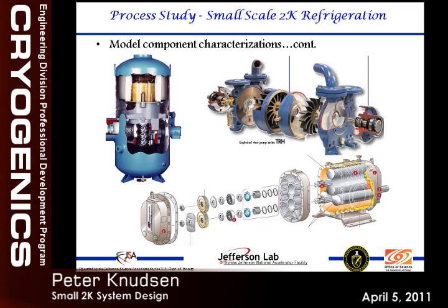See the screw there. You can see the vacuum pumping system. This is a two-stage liquid ring pump. It's got these little paddle wheels that are characteristic of a liquid ring pump. And then this is probably one a lot of you are familiar with. This is a blower. It's got these two things here that rotate around each other. The ones that we use over at CTF are very large. It's maybe a little deceiving, the size here.